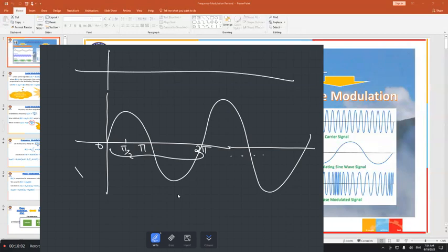See, this is your message signal. Assume this is your message signal. Now, what is done in AM modulation, you all know. Are you thorough with AM modulation? Now, instead of amplitude, I am going to exploit the phase angle. So at this instant, whatever carrier wave I have, its phase angle is varied according to this amplitude. Next instant, the next phase angle of the carrier wave is according to the amplitude of this. Like this, every instantaneous phase angle of the carrier wave is now holding the amplitude of the message signal. Have you understood this?